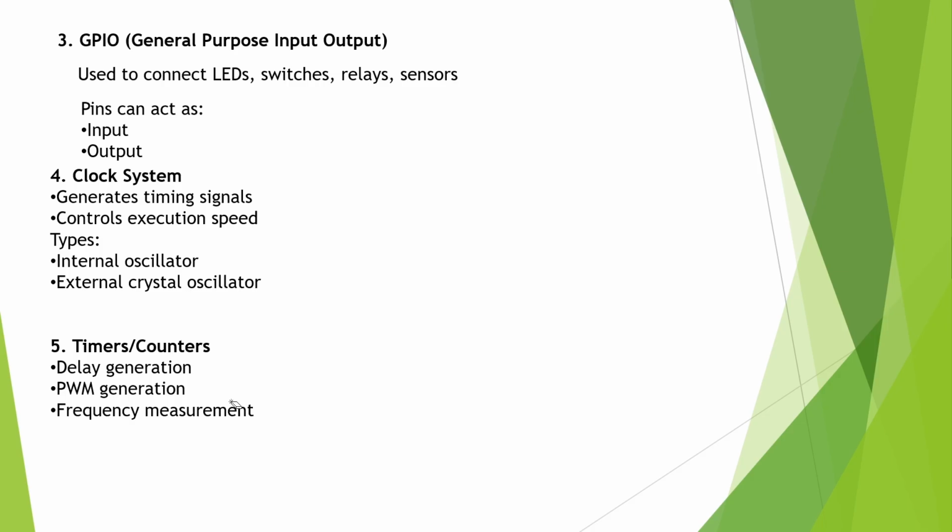It helps to modify the width of the pulses being generated, which gives a clearer signal. To put it in more technical terms, it is controlling the power delivery to a motor or any other peripheral. PWM is generally used for power control. You can control the speed of a motor with the help of a PWM signal.